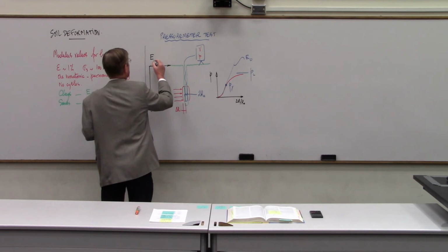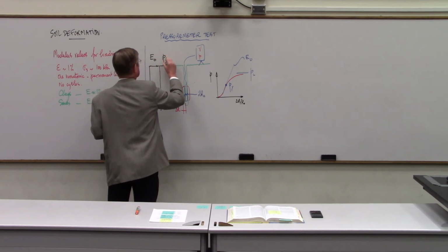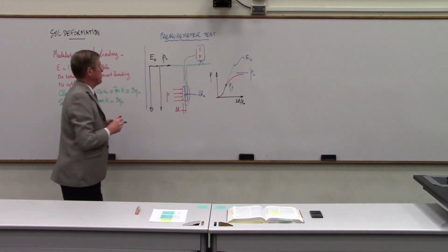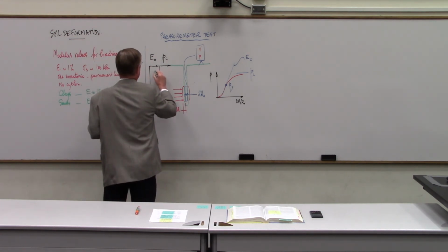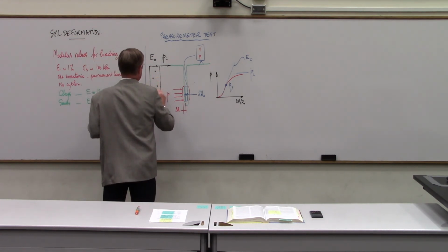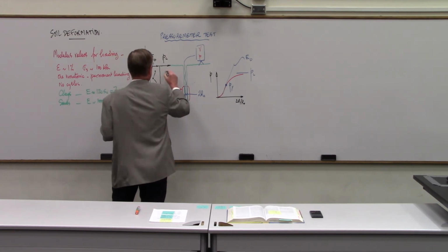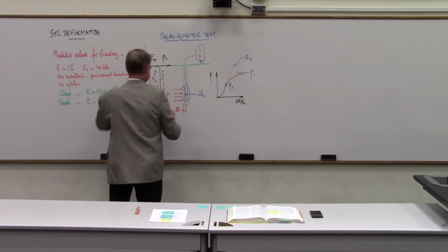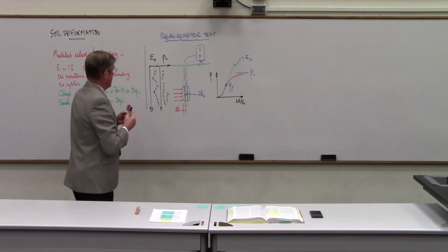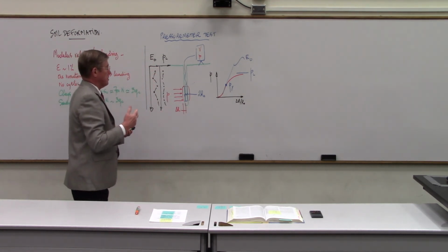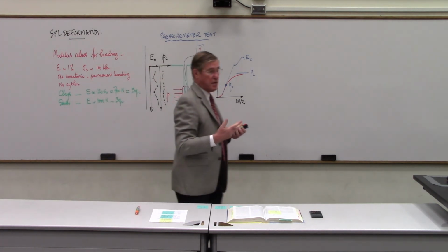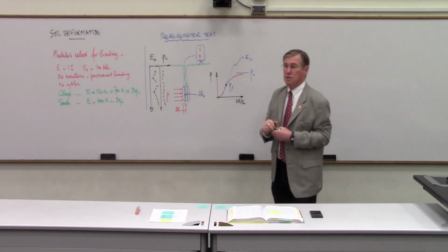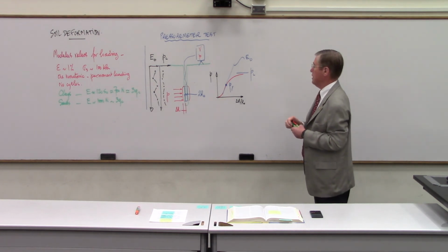And then we will also plot PL. So you get some values that are right here, right here, right here, and then you get a profile of strength of the material, and then you get something similar for the limit pressures and so on. This is one of the rare in situ tests that actually gives you a modulus that is directly measured.